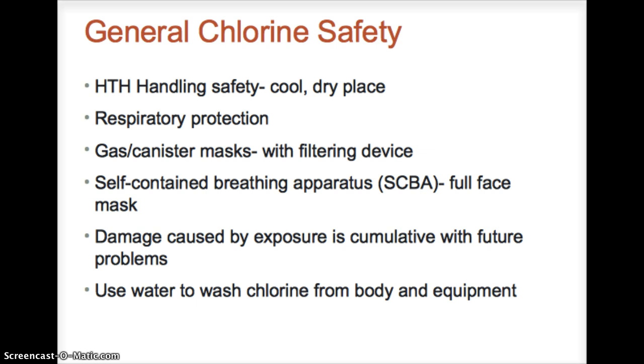So for handling HTH chlorine, you just want to keep it in a cool, dry place. This is solid chlorine. You want to make sure you have respiratory protection: gas or canister masks with a filtering device, self-contained breathing apparatus, SCBA, full face mask. Damage caused by exposure is cumulative with future problems. Use water to wash chlorine from body and equipment. Now this is just general chlorine safety. We have a whole lesson on safety and emergency response later in the class. So just an overview, just a small amount.